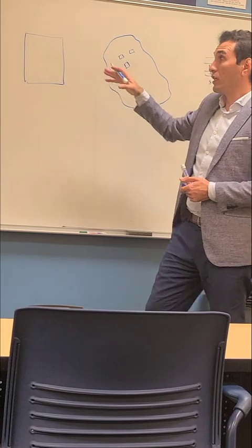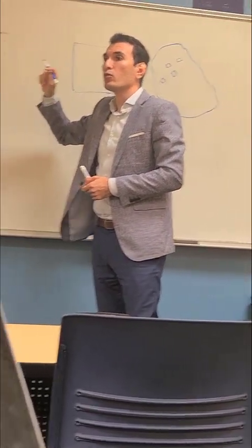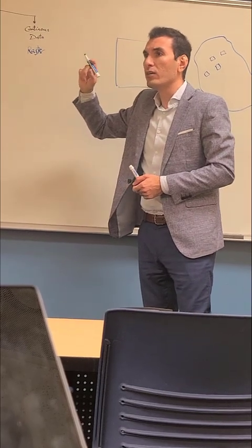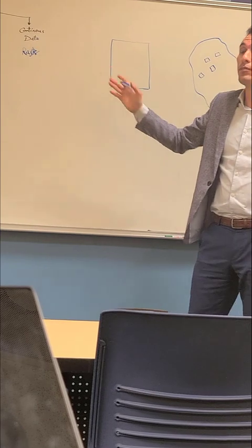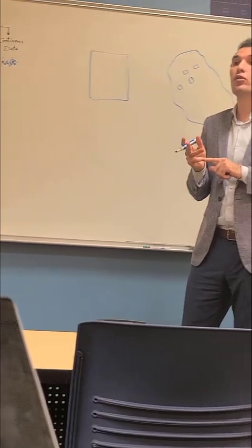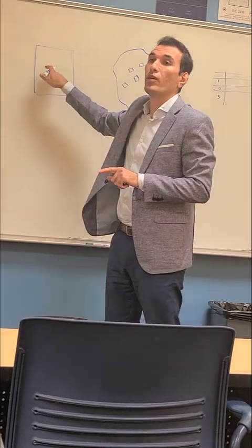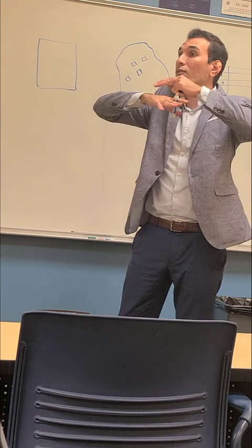And this continuous data has resolution. You can have your resolution very, very fine, like 1 meter, 0.5 meter, or it can be 100 meter, 200 meter. This is how we get data for hazards. Like if we are looking at a flood hazard map, it's in raster data. It tells you what the flood depth is at each location, because the flood depth is continuous.